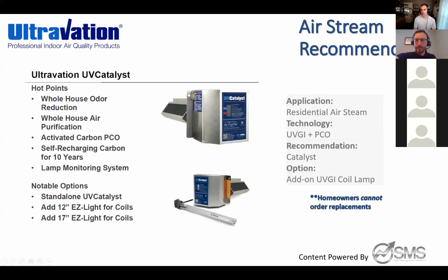Good for now. What size ductwork will that work up through? If you have a 36 by 20 plenum, would you need more than one of those in that plenum? The Induct Supply product like this is designed for up to 5,000 square feet residentially.